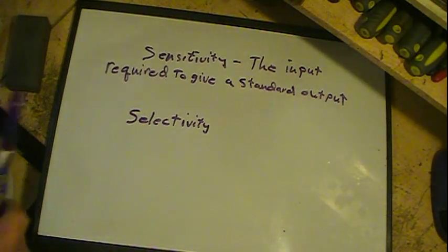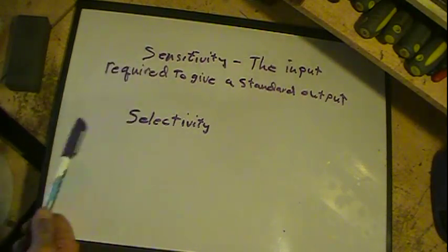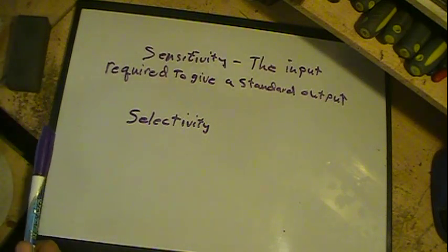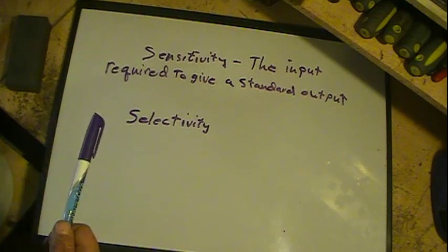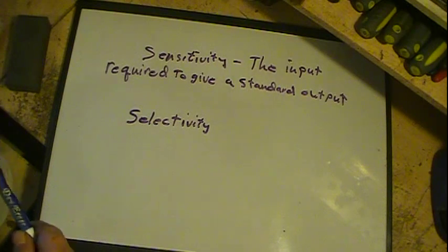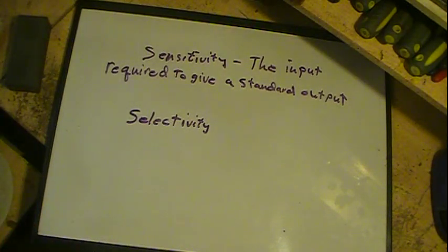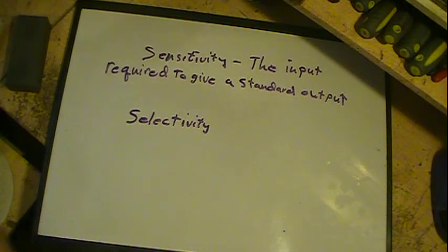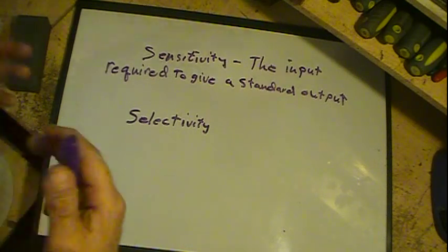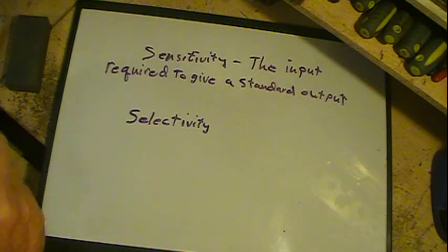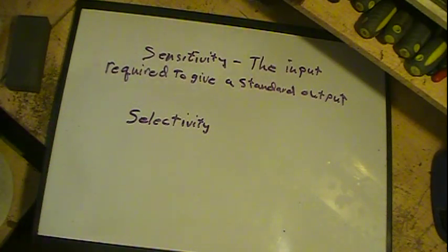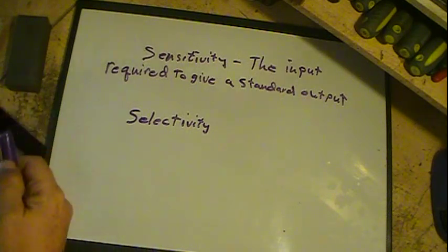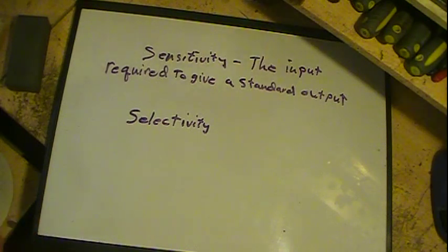Well, what that means basically, in a nutshell, it's actually a measure of how weak of a signal a receiver can pick up legibly, audibly. Not a signal where you have your ear right up against the speaker and you've got it cranked right up and you're going, I think I know what they're saying. No, this has got to be a normal radio signal or standard output, wherever you're comfortable sitting listening to that radio: the weakest signal that you can tune in and hear sitting at that spot with a relatively normal volume level, not so high that it may be distorting or pushing the speaker to its ultimate end.